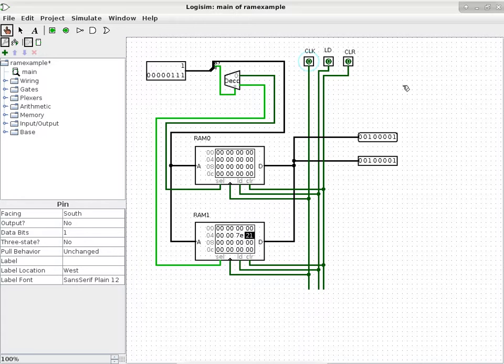What else can we do to speed up this operation? Remember, even with a counter on the RAM chip itself, you just need to increment the counter every time you do a low to high clock transition. It saves you time because you don't have to re-specify the address line anymore. But it's still kind of slow, because when the clock goes from 0 to 1, it has to go back to 0 before it can go from 0 to 1 again. Does it make sense? If you do a time plot of the clock line, it goes like this, but the change of the RAM content can only happen here, here, here, and so on.